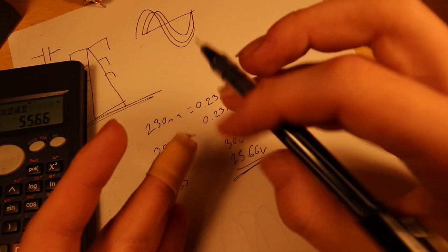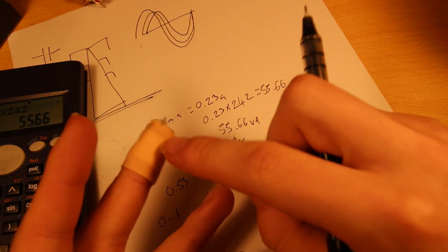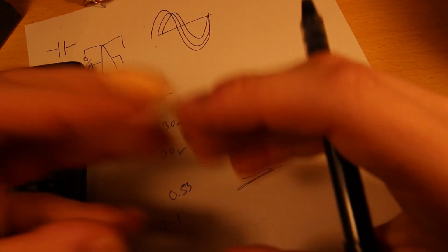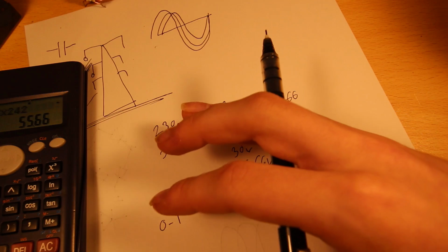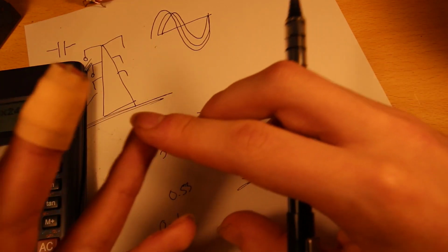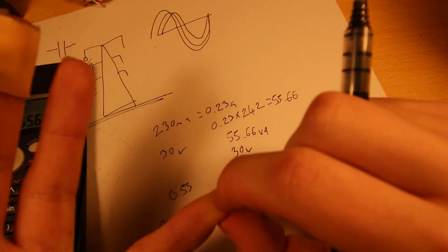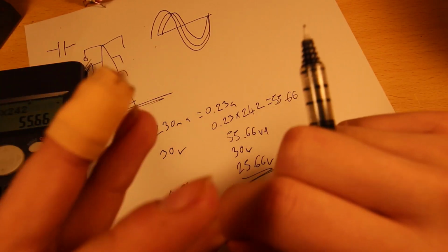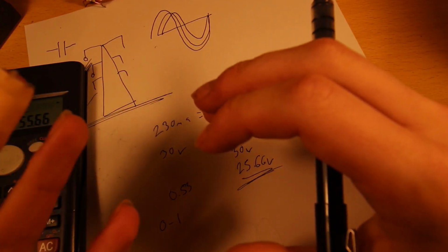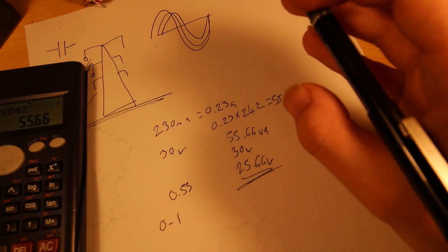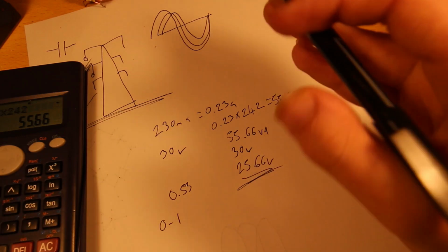If you transmit DC, the only losses you have are corona discharge related losses, which is where the power basically conducts through the air to Earth, and DC resistive losses. You also have the conversion losses for going between AC and DC on each end, but those are fairly minor in comparison to the other stuff. Well, I say they're fairly minor. They're usually 90-95% efficient, so that's not much.